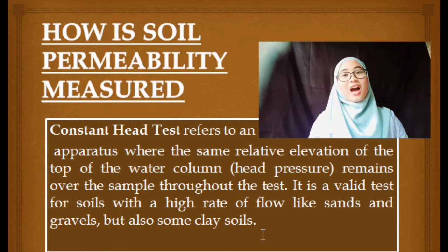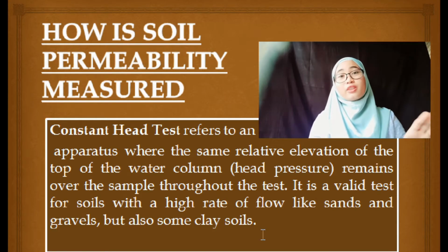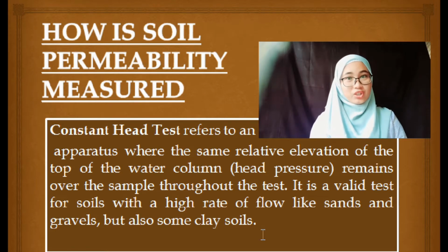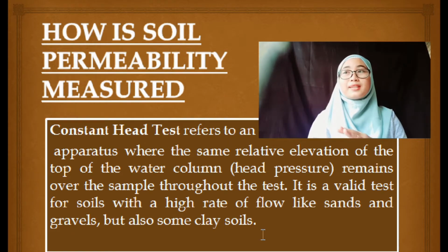So, how is soil permeability measured? The first thing we have to know is what the constant head test is. This test refers to an apparatus where the same relative elevation of the top of the water column, the head pressure, remains over the sample throughout the test. It is a valid test for soils with a high flow rate like sands and gravels, and sometimes some clay soil.